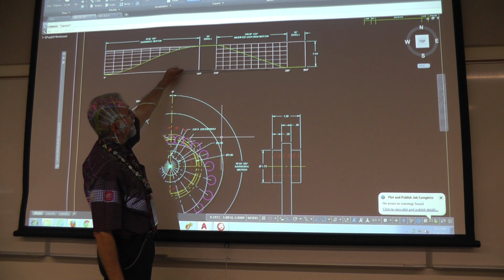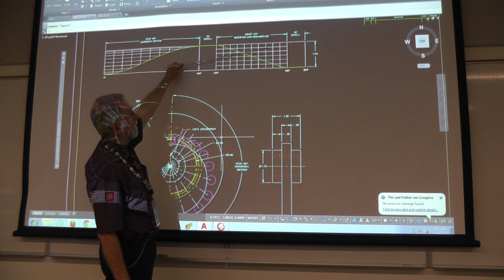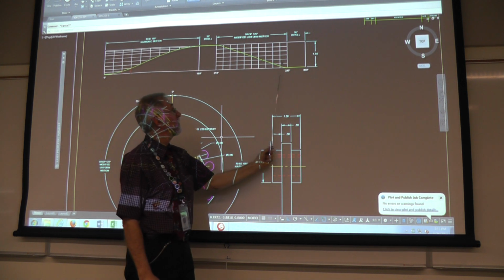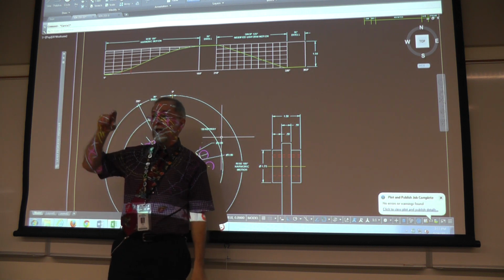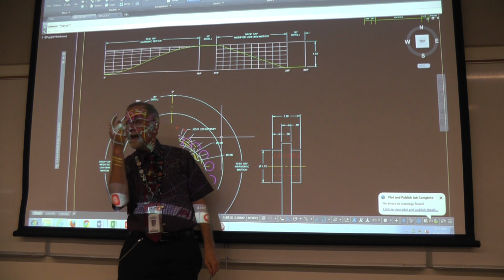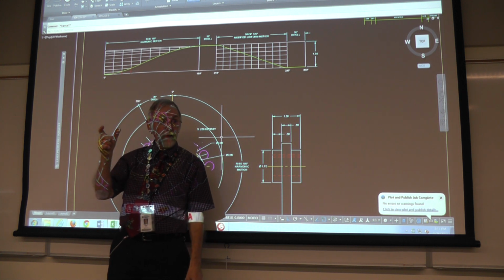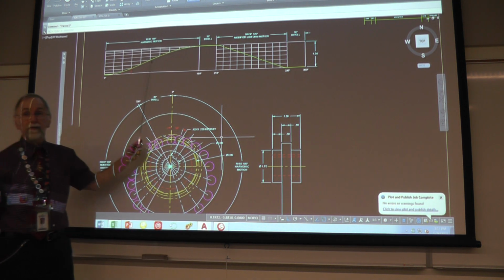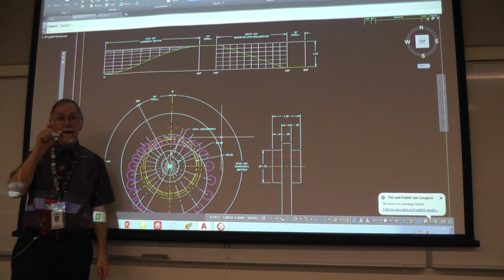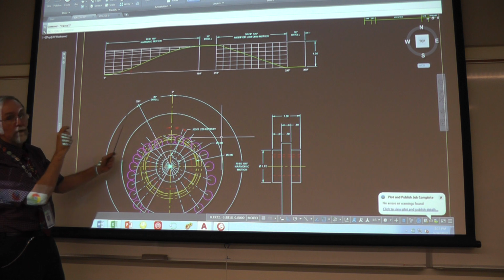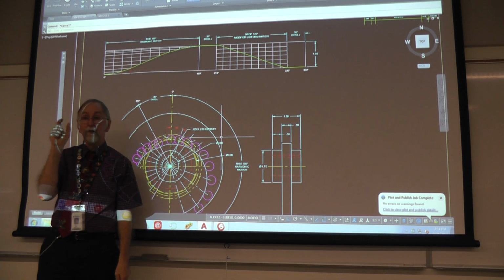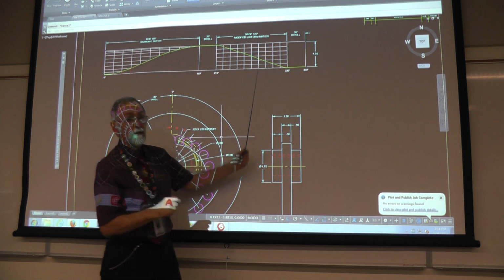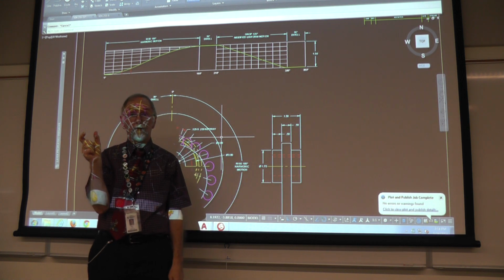This modified uniform motion has 1, 2, 3, 4, 5, 6 vertical increments in it, but I still need to have 10 increments in this direction for accuracy in trying to create the profile edge of the plate cam itself. If this is 180 degrees divided up into 10 equal increments, how many? 180 degrees divided by 10 makes 18-degree increments. That's what came out of the textbook. If I take 120 degrees and divide it by 10, I get 12-degree increments.